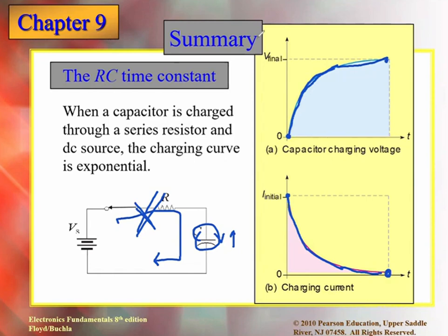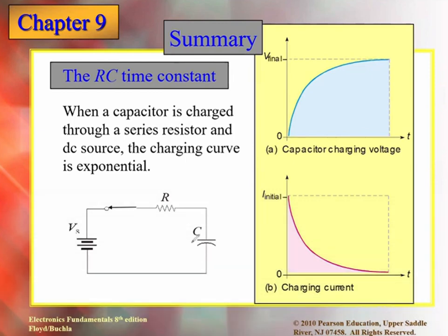Is it clear to all of you? Easy to understand the concept? Clear. Okay, so it is just a concept. As I told you, when it is charging, it keeps allowing the flow of current through it, and when the current is passing through the capacitor, the voltage across it keeps building exponentially. All right, and current keeps decreasing exponentially. Fully charged means current is 0. No current will flow at all once the capacitor is fully charged.